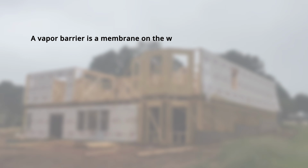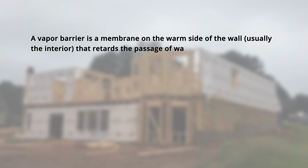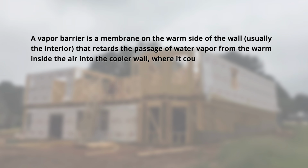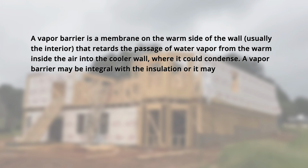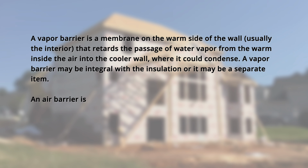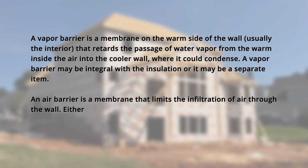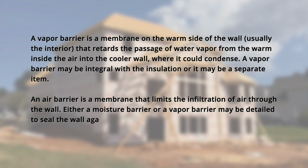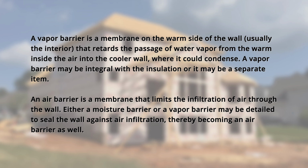Moisture and air barriers. A vapor barrier is a membrane on the warm side of the wall, usually the interior, that retards the passage of water vapor from the warm inside air into the cooler wall, where it could condense. The vapor barrier may be integral with the insulation or may be a separate item. An air barrier is a membrane that limits the infiltration of air through the wall. Either a moisture barrier or a vapor barrier may be detailed to seal the wall against air infiltration, thereby becoming an air barrier as well.